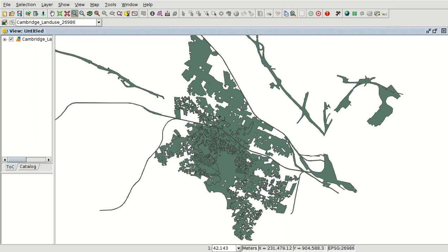We can reproject it on the fly, but if we work with geoprocesses, for example, we will have problems because that layer is in the original reference system. So the coordinates are different. If we edit this layer reprojected on the fly, or we use a geoprocess, we can have problems. So we need to have the layer in the same reference system as the view.